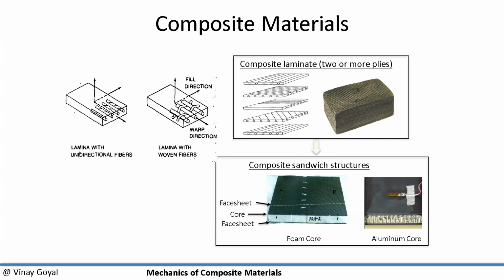For example, in aircraft applications, if I select an aluminum core for the tail, what's going to happen is that aluminum could get corroded. So maybe you want to select a different aluminum that's more resistant to corrosion. Foam, for example, is a material that can absorb a lot of moisture and it can have strength reduction as a consequence. Foam core may not be good at very cold temperatures, it can start cracking. It could be quite degraded at very hot temperatures.